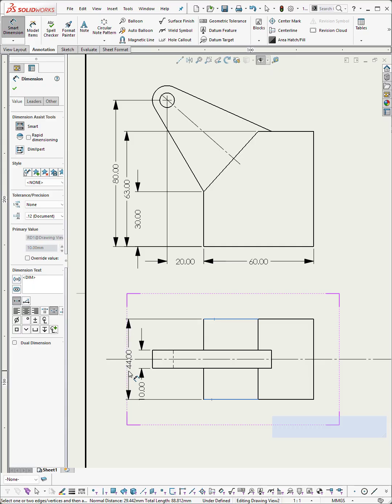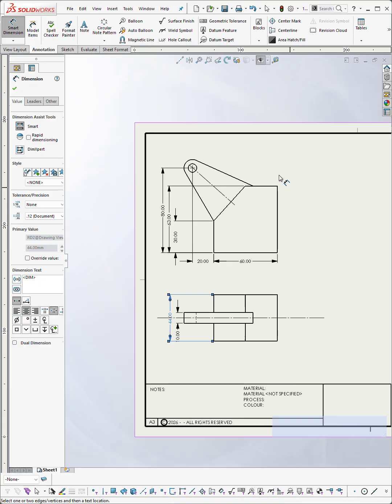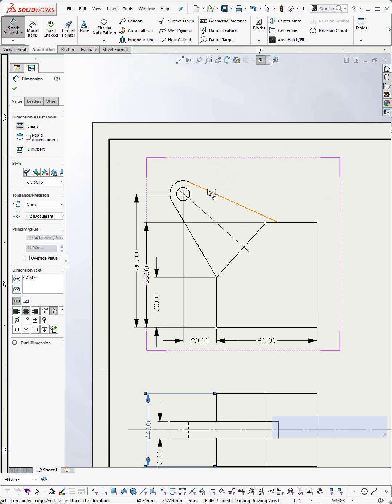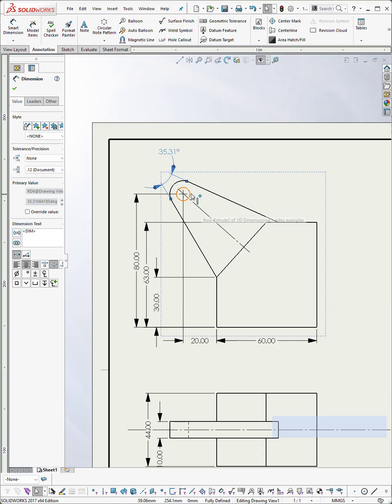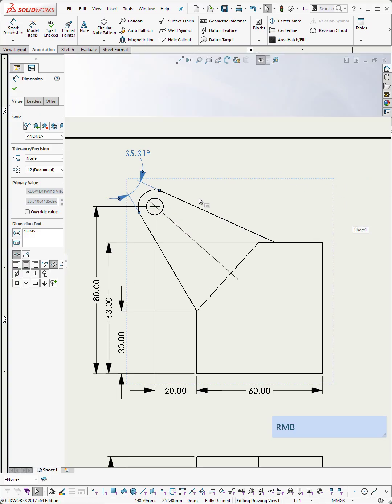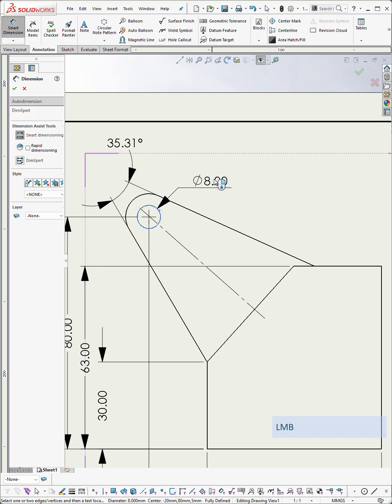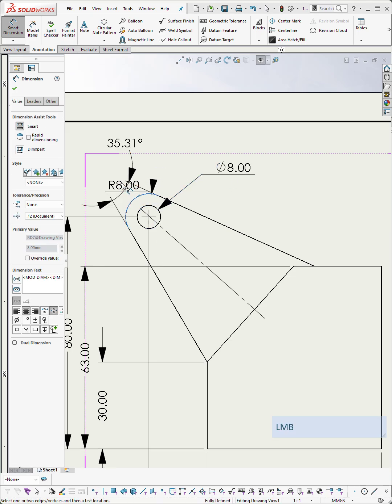So whatever dimension you see, divide it by 2 to get whatever the distance is from the axis to one end or the other. And then from here, oh yes, we need an angle in here. So let's just grab one line, two lines, drag this out, and then you can just arrange this a bit better. And that is actually sufficient, other than the size dimensions, to dimension almost everything here.